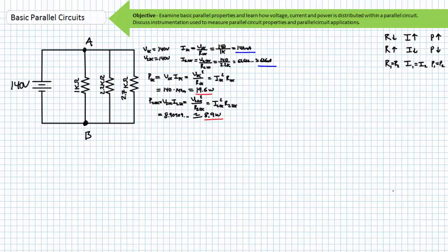This again reinforces our earlier understanding of parallel relationships we gained in the fixed resistors lecture. Anytime another resistor enters a parallel relationship, the total resistance seen by the source goes down because there is another path for current. Source current increases because the total resistance decreases.